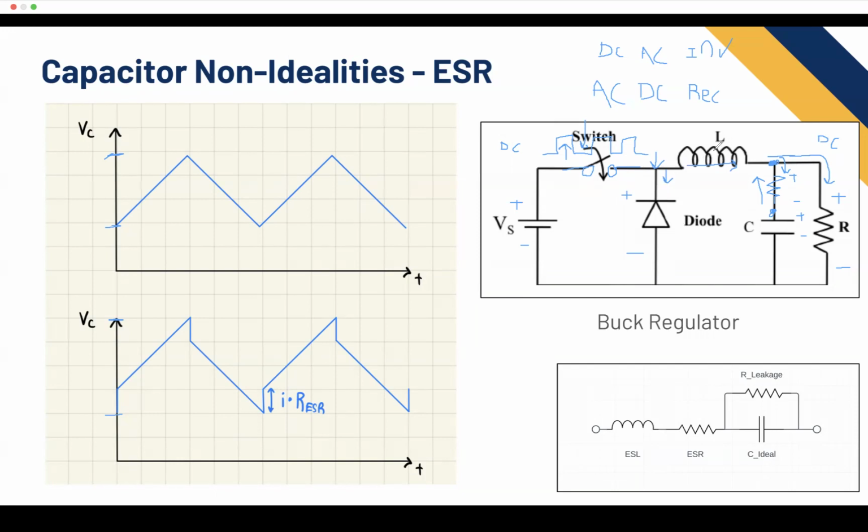So the inductor is pulling a bunch of current, right? Because it was pulling current from the source, DS, and suddenly the switch opened, and there's nowhere else to pull the current from, but the inductor doesn't like that, so current keeps going and it has to come from somewhere. So it'll drop this node voltage all the way down until the diode turns on and becomes a short circuit.